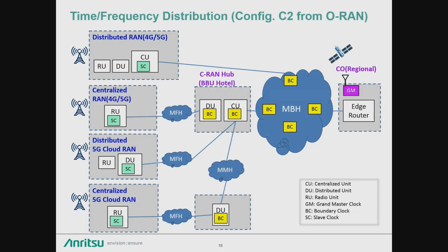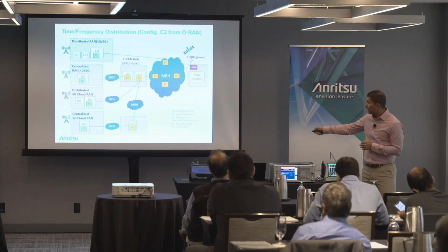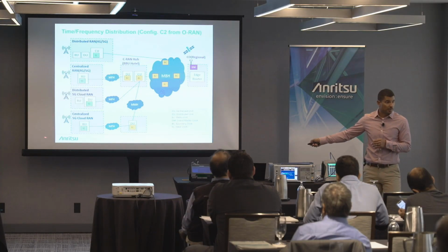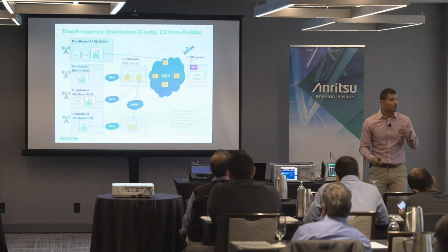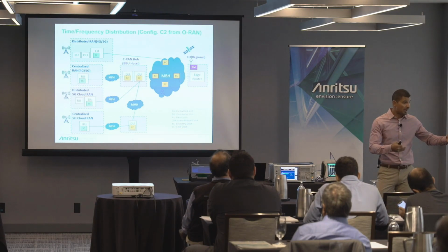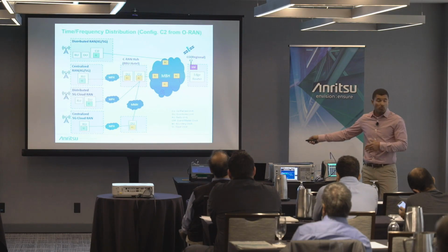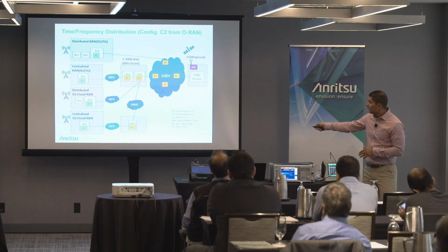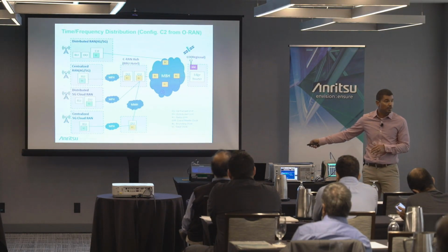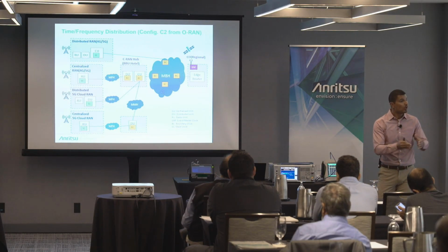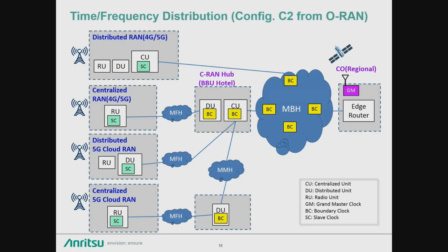If this boundary clock going through this route is exceeding its 1 microsecond, 1.1 microsecond, let's say, of timing error, it has too many hops, and this one has the right amount, it does not exceed it, this would still look synchronized, where this one would generate alarms. And now these two would not be able to be, even if they're geographically close together or spread apart, their timing link is what's causing them to be outside of the 3 microseconds.